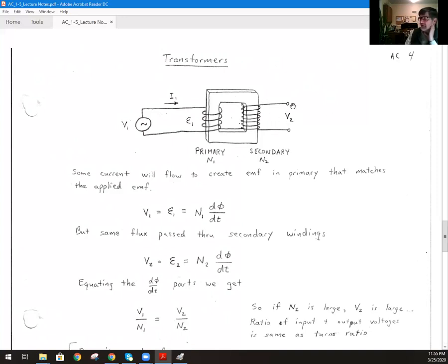So that gives you an idea of why you would have an alternating voltage coming out on this side, and perhaps even explains why nothing happens if you have DC. You apply DC on here and you don't get anything at the output. It's only when you first apply it or when you take it away that you get something at the output.